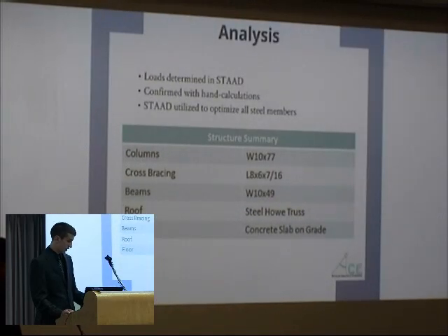Our analysis included determining our member loads. We chose our loadings with LRFD, and we applied them. We confirmed them with hand calculations, and then we utilized STAAD to optimize the members. And when we optimized the members, we found the worst case and carried it through the structure for simplicity of construction.